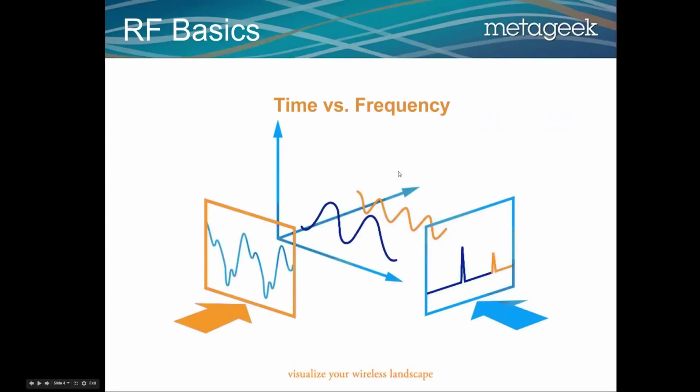Okay, so spectrum analysis is really quite a simple thing. We are looking at just RF waves, and we care about the frequency, and we are going to visualize it in a slightly different way. If you look at this blue line, the height of it represents how loud or how powerful it is. This is the measurement of amplitude, and some of you will call this signal strength or dBm.